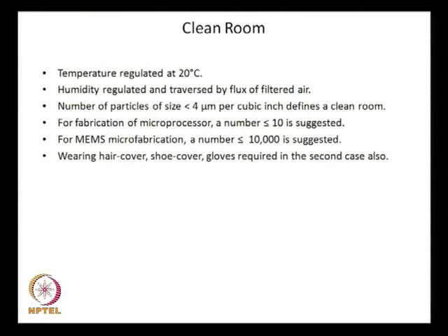Now, before we get into this microfabrication process further, I must tell you, you have heard of the clean room, that you have to have a clean room to do microfabrication jobs. If you go to a definition of a clean room, the temperature has to be regulated at 20 degrees centigrade, and humidity regulated, and it is traversed by a flux of filtered air. Then how do you define a clean room? You must have read about a clean room of type 1, clean room of type 10. So, what is that number?